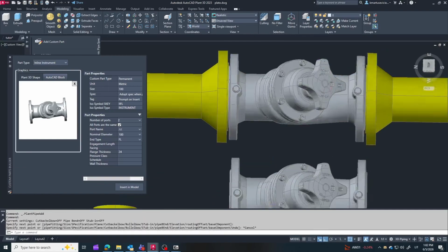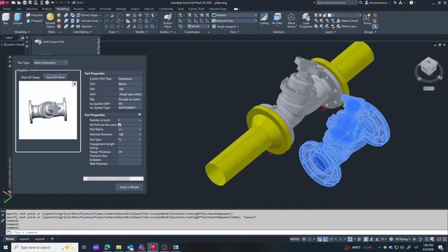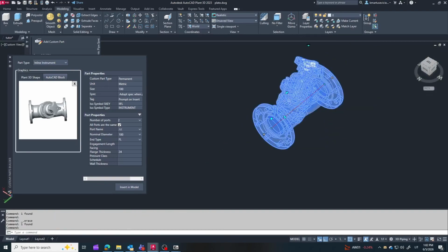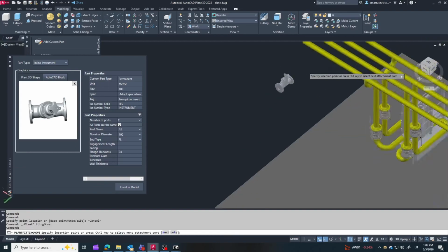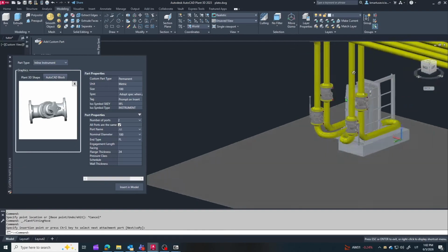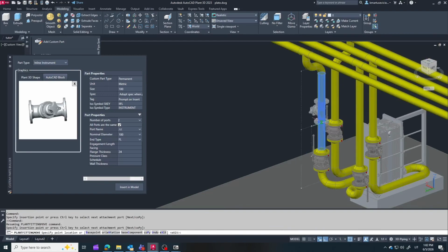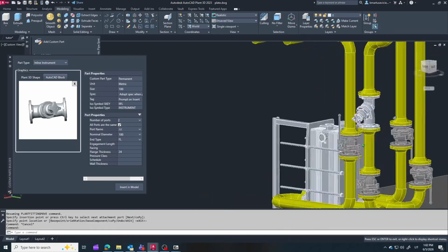The component I'm using here is a manual or static balancing valve. You lock it into position once during the plant commissioning phase. If your facility has highly dynamic loads where flow demands constantly shift, you would step up to an automatic or dynamic balancing valve, which adjusts itself on the fly to handle fluctuating system pressures.